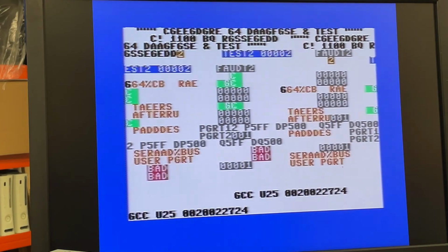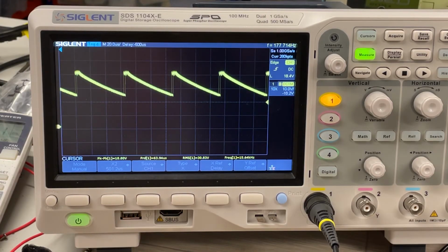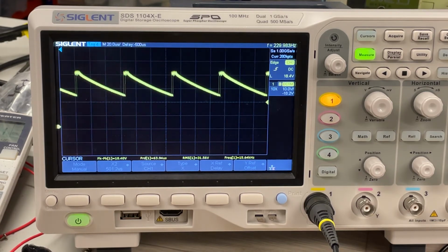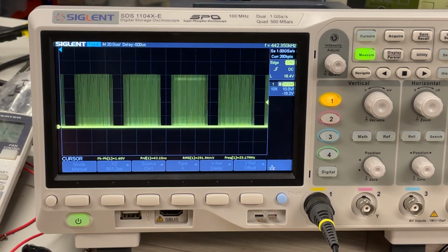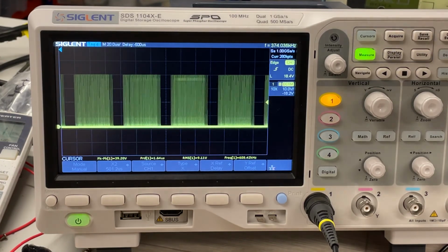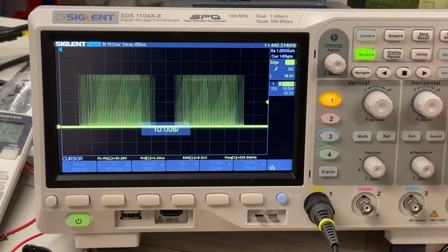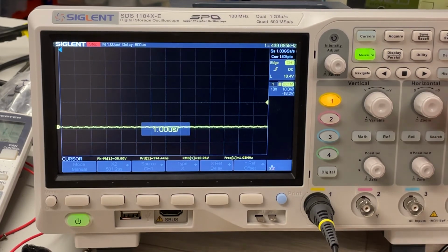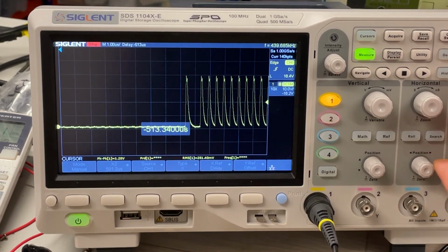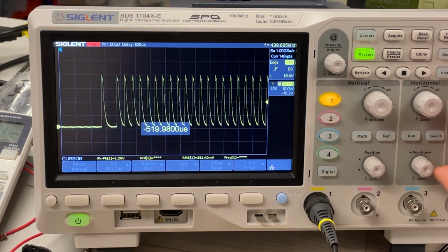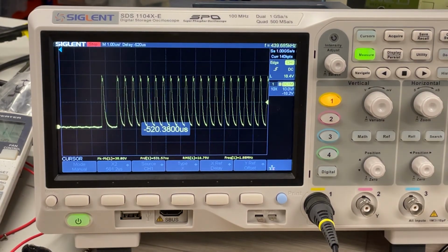Now let's check on the oscilloscope. So this is me probing pin number 12. The video is corrupted, but the moment I'm adding a 1 kilo ohm resistor to the same pin, there you go. The video is back and the line is healthy. Look. It shows this weird waveform, which I feel is still incorrect, but somehow the rest of the system is happy with it. Again, you can see it's not really a square wave, but the video is fine.